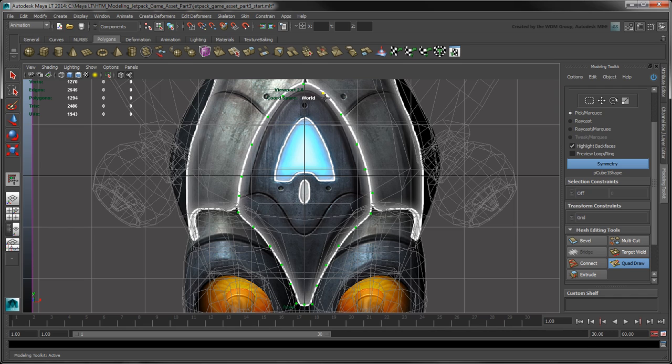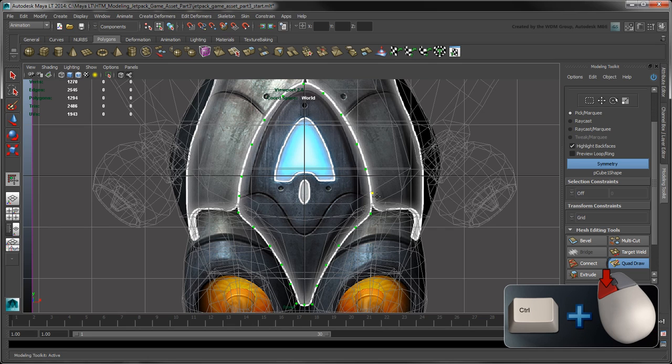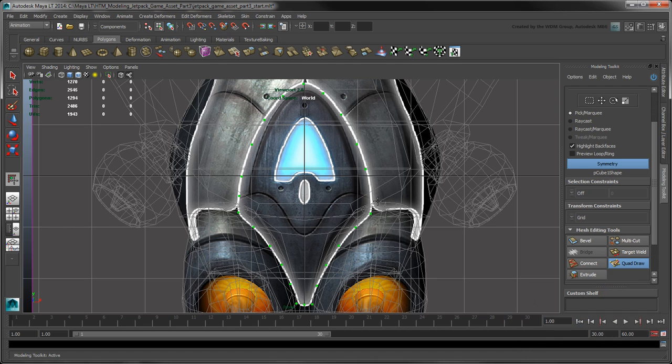At any time, you can reposition a vertex by middle dragging it, or remove it entirely with a control click. Hold Shift to preview the quad-faced polygons defined by your new vertices.